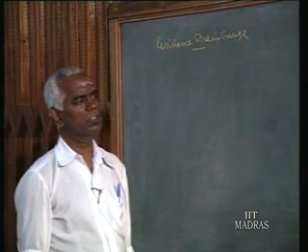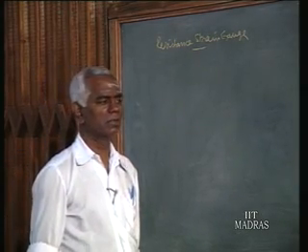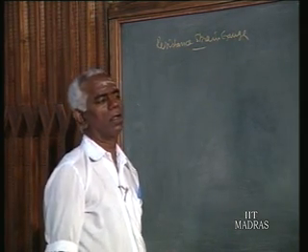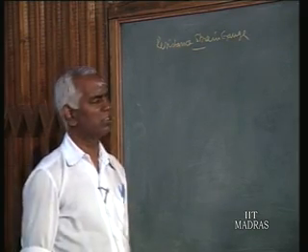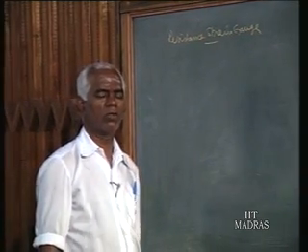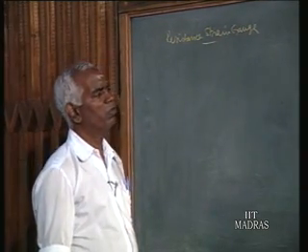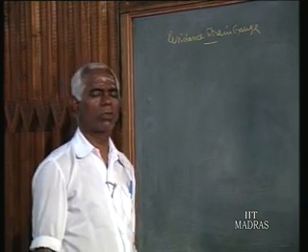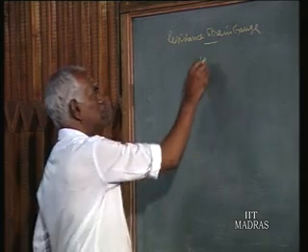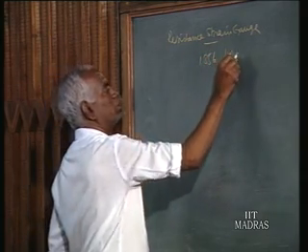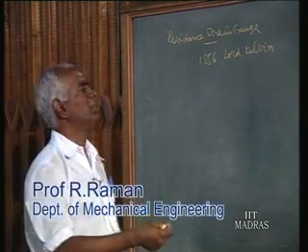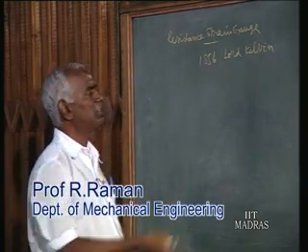A resistance potentiometer, what you have seen, is a very old, primitive device, but still it is used nowadays. The next form of usage of resistance is the resistance strain gauge. It is very widely used in mechanical engineering as well as in civil engineering to find out the stress in beams at different points. This effect was found out by Lord Kelvin in the year 1856. When a metallic wire is strained, the resistance is changed. That is the physical effect that is being made use of there.